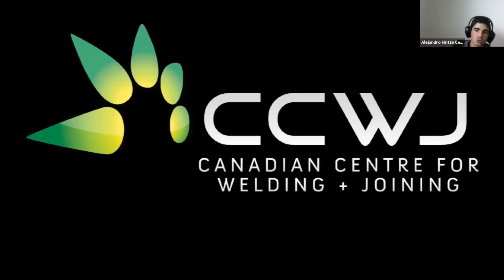So this is good because you can weld in any position. Of course, this is a semi-automated process because we are welding with a system, but you can set up these parameters and weld with your hand. It has a low heat input, and the electrode efficiency is very high because you're literally sticking the electrode into the puddle, right? The bad thing is you can't weld thick plates. It's mostly used for thin sections, because if not, it can result in incomplete fusion or penetration. And spatter can be high. It's not the highest, but spatter can be a problem in this type of metal transfer.